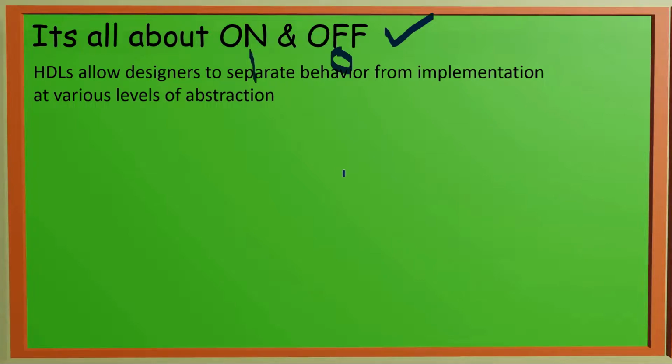So let us see the flow, how we get there. At the basic level, we have the transistor. We can have various gates by using transistors. For example, this particular circuit is for an inverter, that is a NOT gate. That means if input is 0, output should be 1. If input is 1, output should be 0. This is one kind of gate.